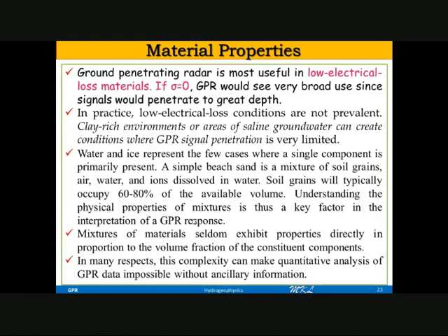So suppose in a clay sand, 40% of clay is there. In that proportion, the GPR signal will be attenuated. So 30 to 40% of the GPR signal will be attenuated in that layer, for a simple understanding. That is what is written here.